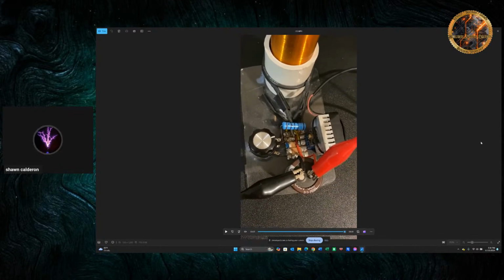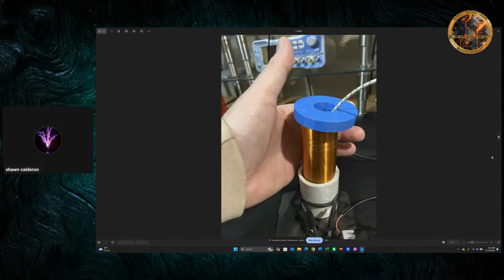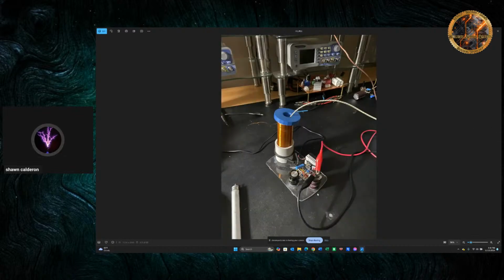And there it is. One of the ways I build circuit boards is it's a piece of copper here with fiberglass under it. I take my grinding wheel and I grind out lines, and then I just solder to the lines. Yeah, it's not very high tech here, very low tech. Showing you how dinky the coil is, it just fits in the palm of my hand. I don't even have a power input. I just connect the power supply to an old capacitor from a stereo at the thrift store.